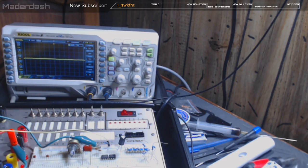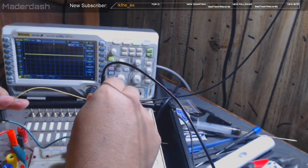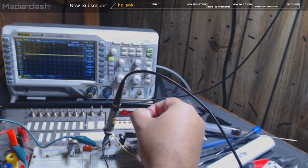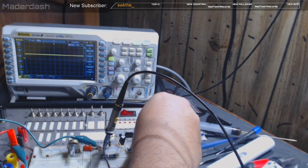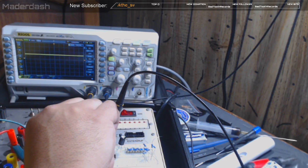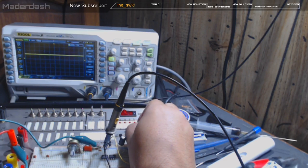Then if I'm right, we'll pull the probe high. I still think you are hacking NASA now. No, not right now. Right now the probe is pulled high. So if I find a ground pin, it should pull the probe low. See, that pin's not ground, or it'd be pulled low right now. Just to test this, if I find a ground, let's see right here. Yeah, see, I hit ground and that pin gets pulled low. So if I find a ground pin, it should automatically get pulled low.